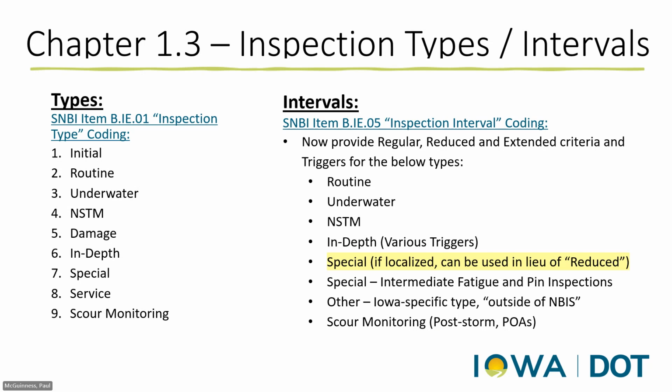And speaking of monitoring, actually, scour monitoring inspections. These are inspections of bridges over water after a triggering rain or flood event, as described in the bridge's scour plan of action. So basically, once that rain event or flood comes, you're going to go out to the structure when waters go down a little bit to check for undermining, scour, and structure stability. Next slide.